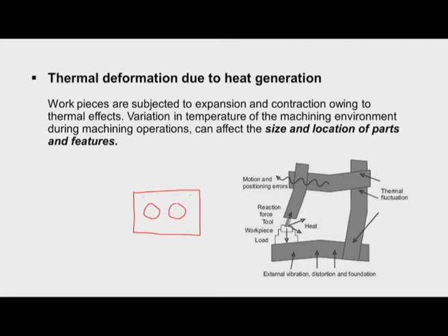Now because of the milling the workpiece is in a heated condition, and immediately it goes for the drilling operation. So he puts the drill, and there is some tolerance for the center distance. Now once the drilling is over, the workpiece is removed, and then when it cools, because of the contraction the center distance may change.